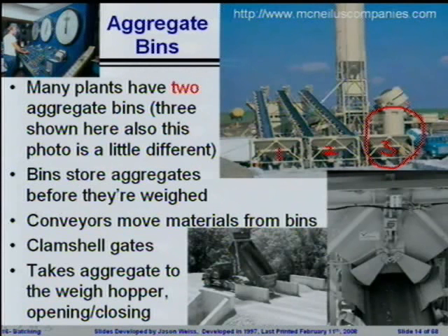So you'll see a lot of people talking about ternary blends of aggregates, 4 blends of aggregates, doing all kinds of different things. A lot of times it's restricted by the equipment that's out there in the industry at the current time, and you need to know what's locally available to the particular regions that you're working in. Now, if you're working in a major metropolitan area, this is not typically going to be a problem. However, if you're working in other areas where 2 bins is typical, you need to work on the assumption that you're going to have 2 bins.